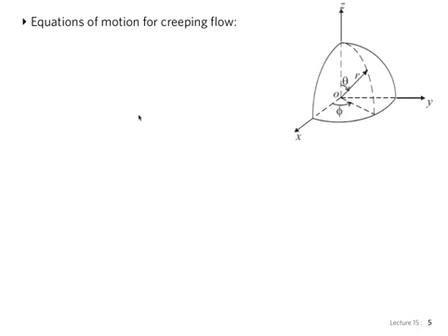So for the case of Stokes flow, I want to give you a little bit of an idea of what results we can get mathematically. Suppose we're going to look at a very famous result for Stokes flow, which is the case of a sphere. So we consider a sphere of radius a, which is like imagine a grain of sand. This is one of the typical applications, a grain of sand which is settling in water, say. This is completely governed by Stokes flow because of the length scales. And we're going to assume steady state.